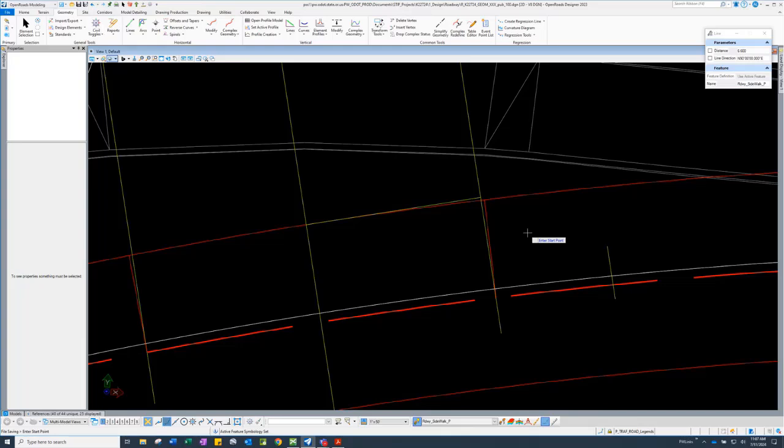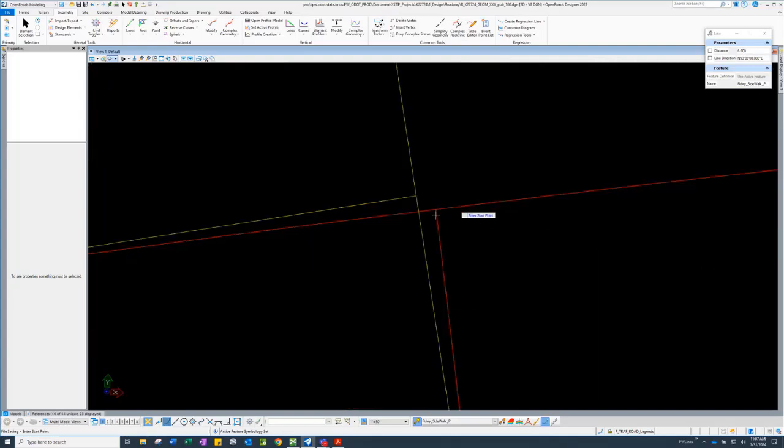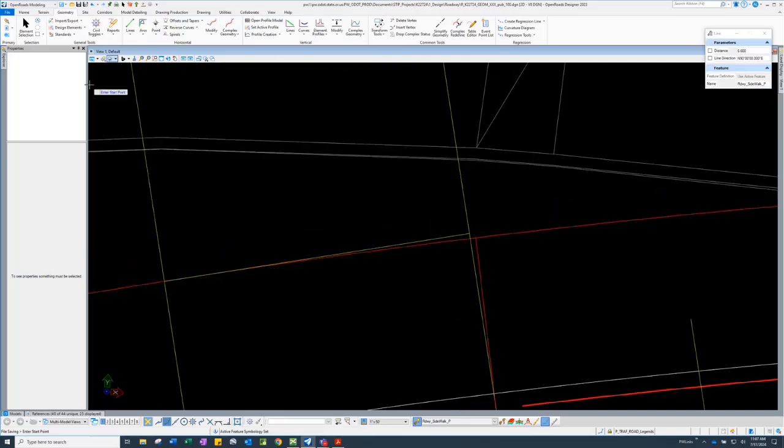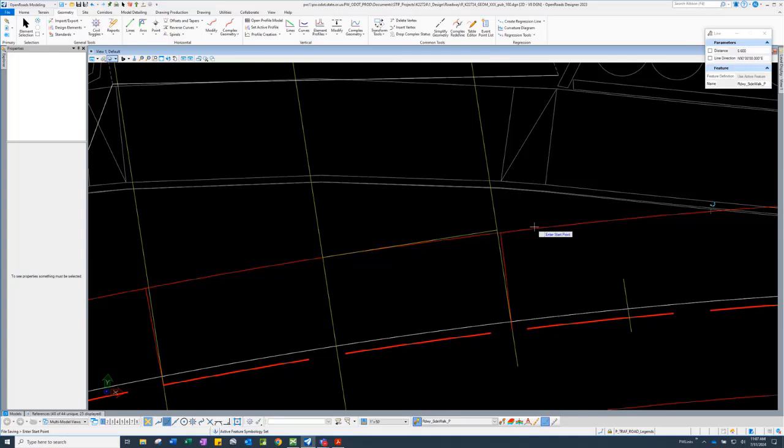So this will match up with your template drops in your corridor file. This is how to display them correctly. As you can see, if you use the partial offset line and just drew over the top of it, there is an actual gap. There's a difference. And to get that to model is very hard. So, and I'm not sure I would not model that way. I would pick a different driveway, because I don't believe they're going to construct it. They're going to construct it with a perpendicular line.